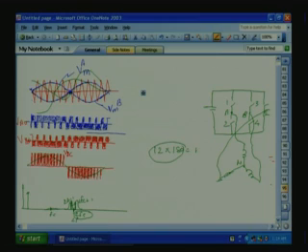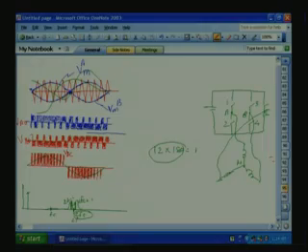This way we will be controlling the ABC sequence. As I told, the whole purpose was to control the low order harmonics and also to control the fundamental. What we achieved is that we have introduced notches instead of the rectangular pulse.